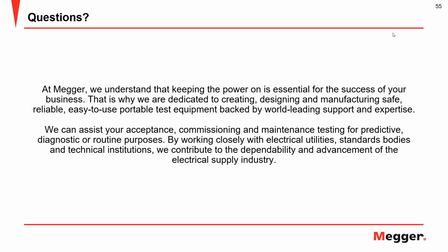This is why it's still recognized by various international test standards. They say if you have old paper cables and you want to do a DC test, that's okay, even though the AC test would be more beneficial to actually find certain faults.